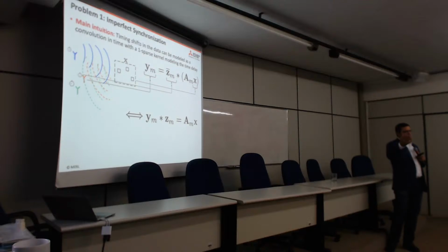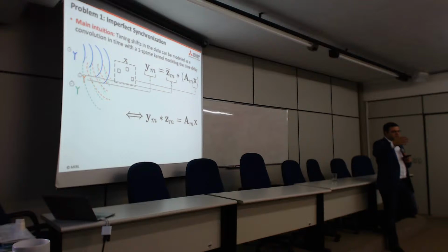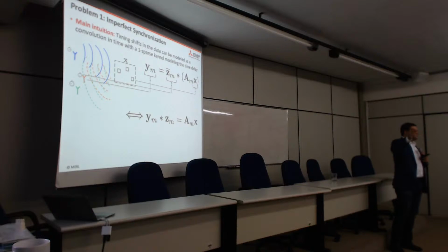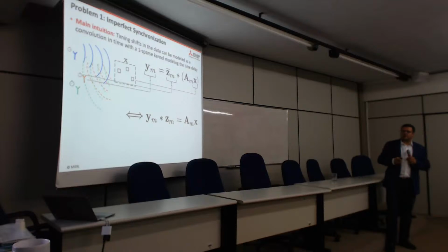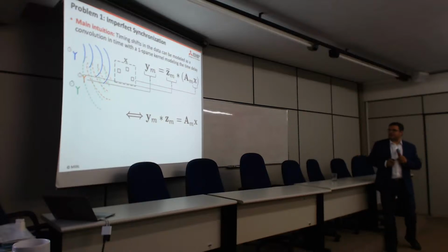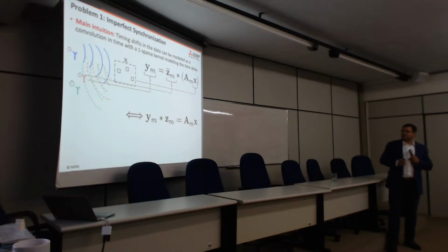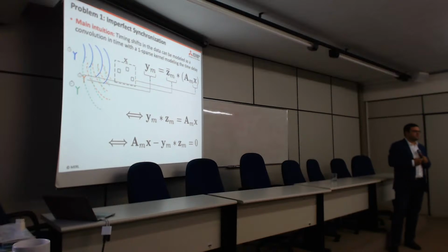I will not try to advance or delay my ideal signal to explain the data. What I'll try to do is shift my data to be compatible with the signal I recover. So it stops being multiplicatively entangled with X, and you bring that to the other side, and you say, well, this system, if I take those two unknowns, should give me 0.